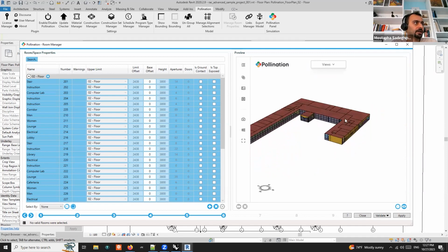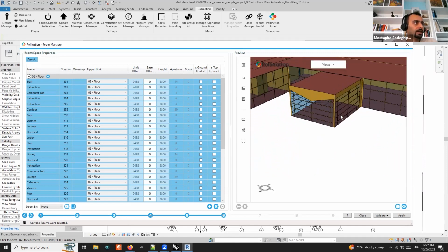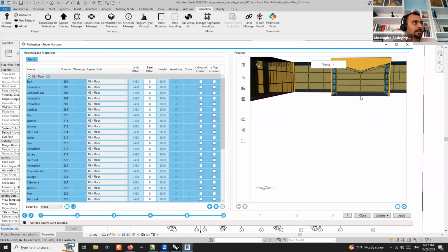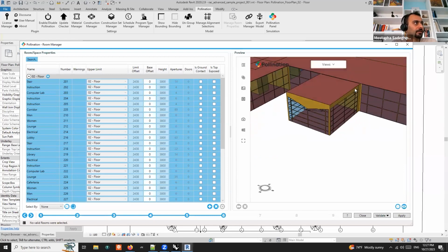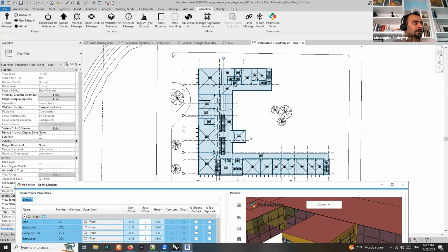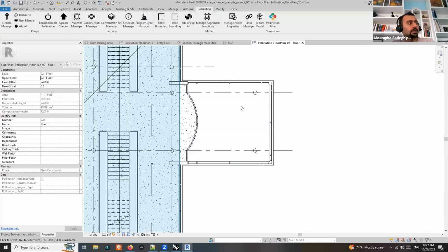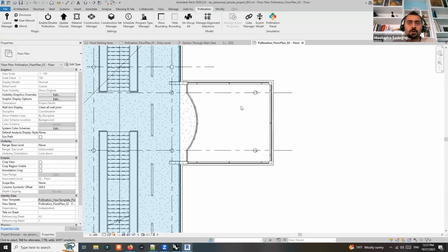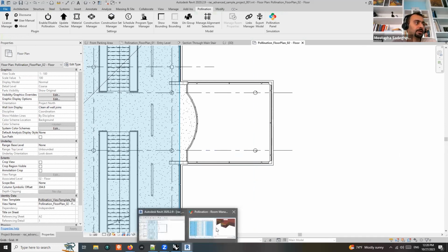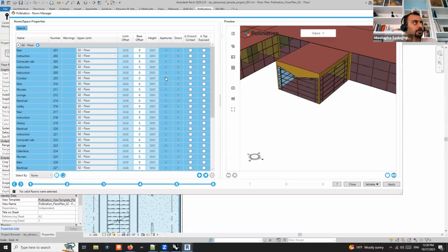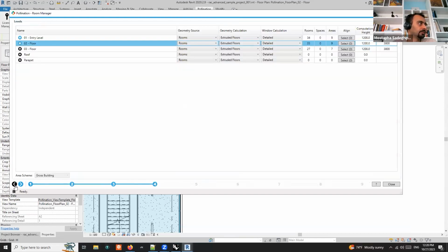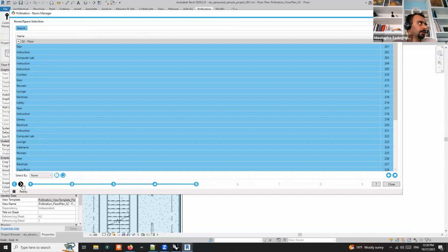So this is interesting. I see everything here. There is another instance of this lobby here in level 2, because I did the automatic placement that I don't really need. So I'm going to go here and delete this. And this is why you need to do preview and check every level, because it's very easy to make mistakes when you just go quickly with this kind of stuff, right? So I'll just go back here.